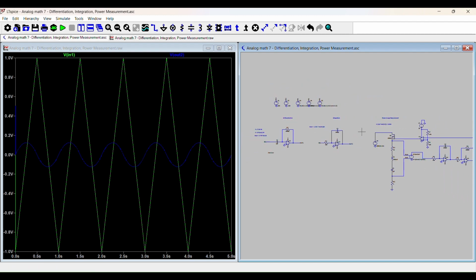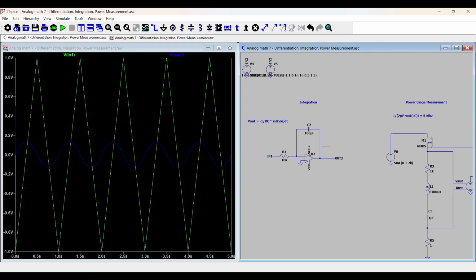Cool. So I just want to quickly talk about what's actually happening on the op-amp. Essentially, there's a current coming in through here, and the op-amp is pulling and pushing the voltage so that the capacitor, when it integrates this voltage change, can produce that current. That's essentially what's happening, and so that's integration.